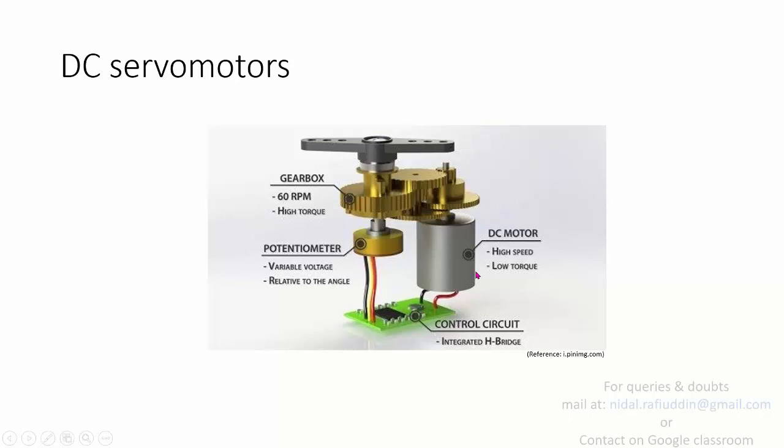Today, if we want to control the motor output using a variable field, we'll keep the armature constant, and the second set of terminals, the field terminals, will be fed with the feedback or error signal. So this motor, if it were a field controlled separately excited motor, should have four terminals.